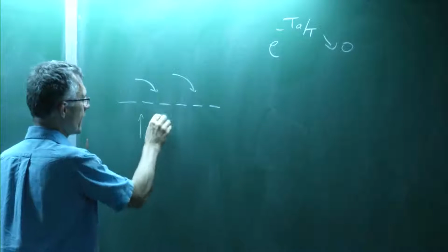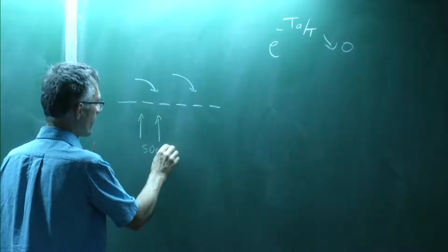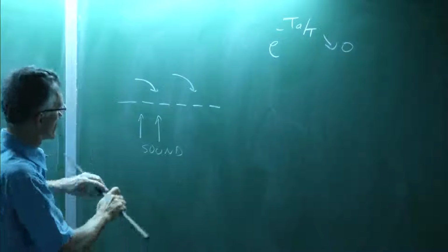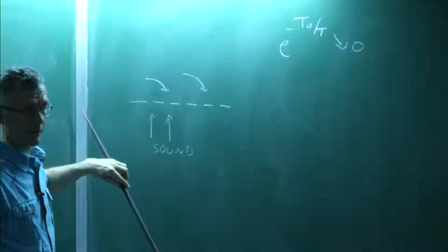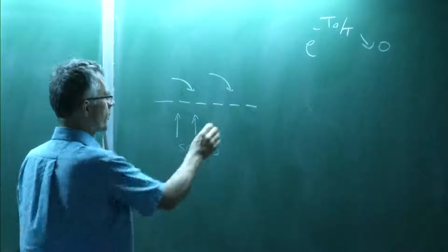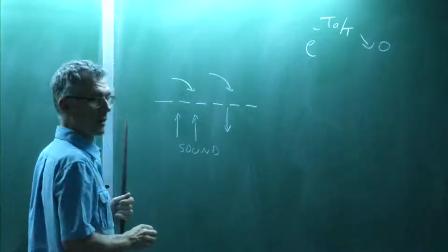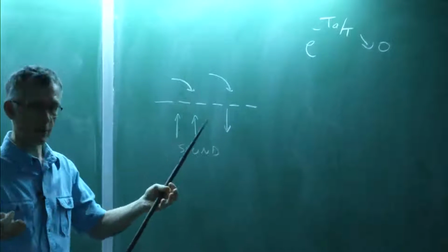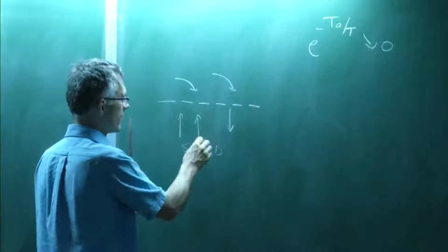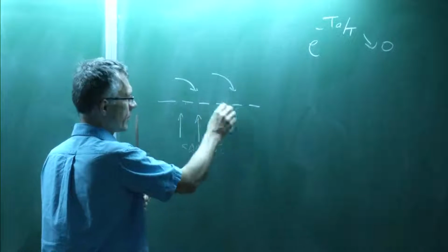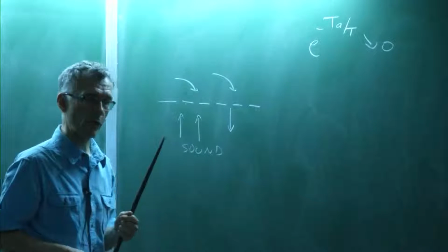It will also change its acoustic properties. Because now if you have a sound wave arriving on a wall with multi-perforation, the reflection coefficient will not be the same. Now you know, because we've done that during the acoustics course, what the reflection coefficient is. That means that the energy which will be sent back to the flow will not be the same.